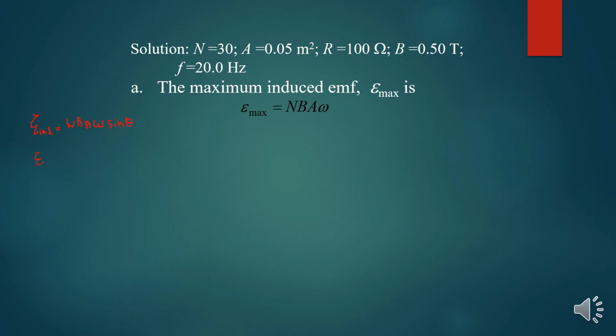The induced EMF will be maximum if sine theta equals 1. So for EMF maximum, the formula now is N B A omega. So this is the formula.